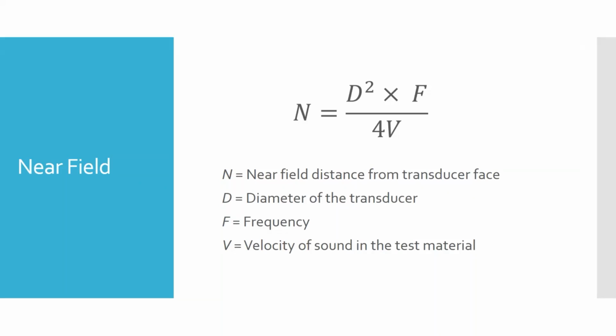Okay, so that top millimeter of our part, we would not be able to reliably find any kind of cracks, discontinuities, or damage. Okay, because of that near field interference that's taking place in that area.